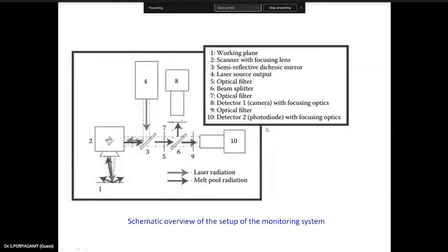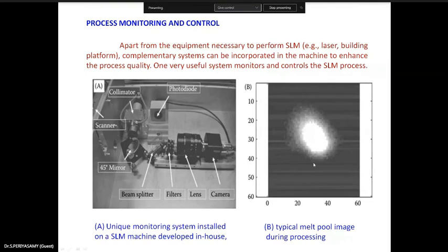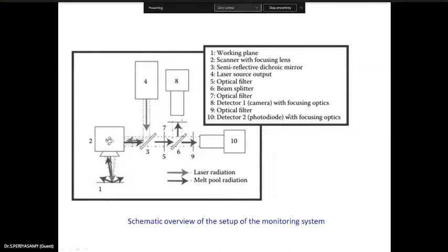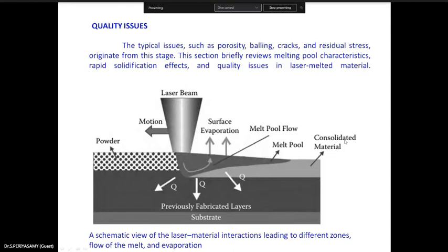That is, whether it has transformed or not. With the powder fusion bed, you can easily find out whether the powder is transforming or not. Then you can control. If it has not transformed, and phase change has not occurred, you have to go for more specific energy, because the energy striking the powder is not enough to melt. Otherwise some particles are melted while others are not, because the focus is somewhat varied.